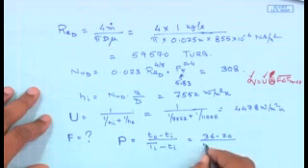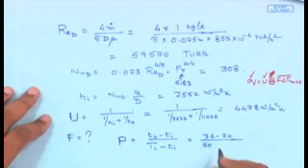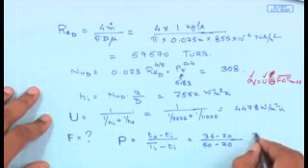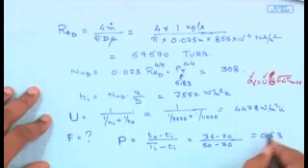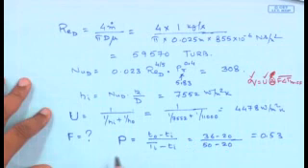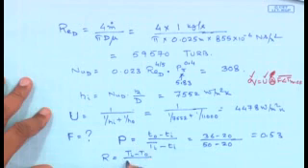The temperature of the hot side is 50. So, this is about 0.53, and the other factor which is defined as R, Ti minus T0 by T0 minus Ti, where capital T refers to the shell side fluid, small t refers to the tube side fluid.